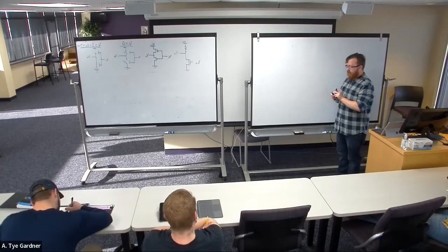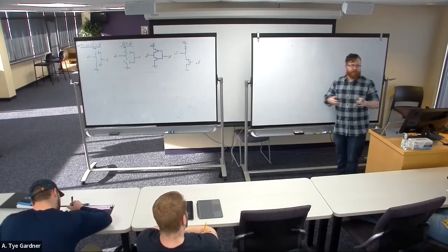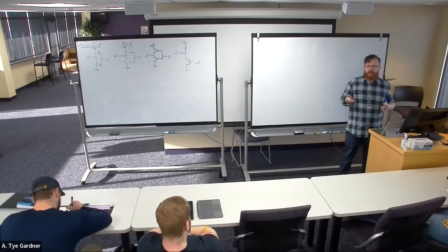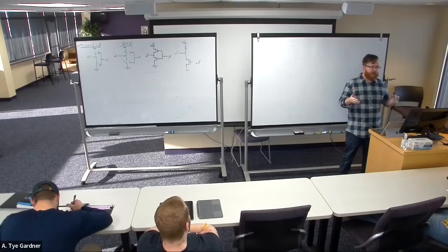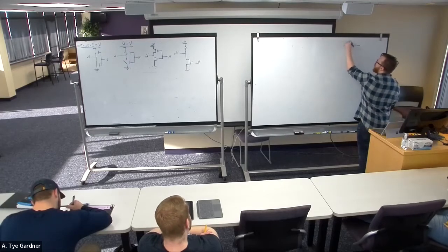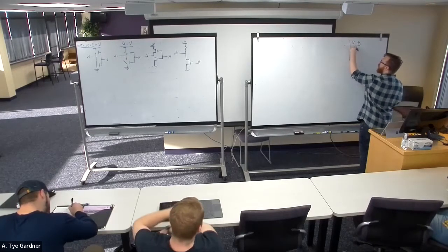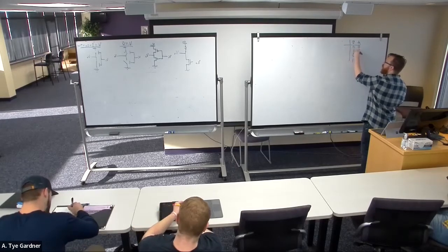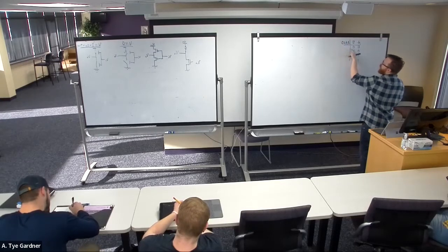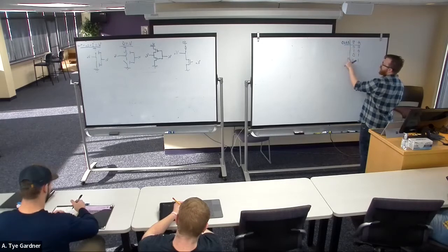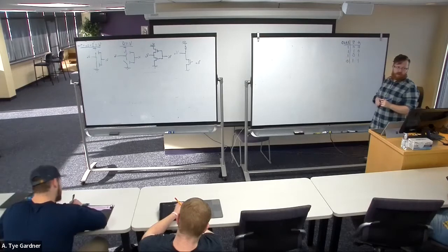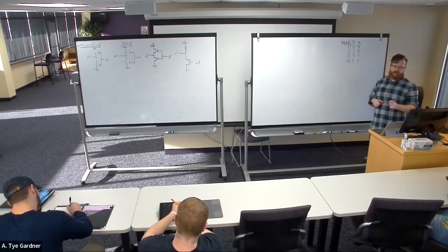So anytime we design a circuit, what we want to do is look at it from the perspective of the pull-up and the pull-down situation. I said we're going to start with NAND. AND would have a 1 and the rest zeros, so NAND is 1, 1, 1, 0. This is our truth table for the NAND gate.